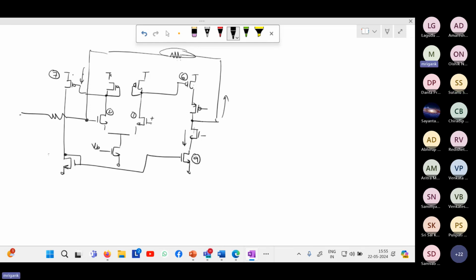Okay, if I start going deep into the theory of feedback, it will take a lot of time, but very quickly I can explain why this is a voltage sensing current feedback mechanism. For a current feedback, what is the condition? For current feedback, the feedback connection is at the same terminal as the input, right? So here the feedback connection is on the same terminal as the input.